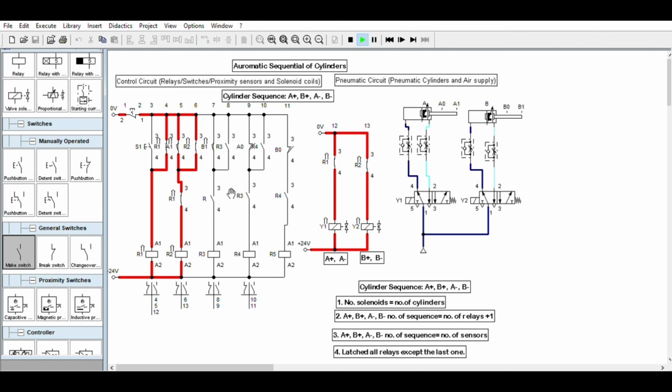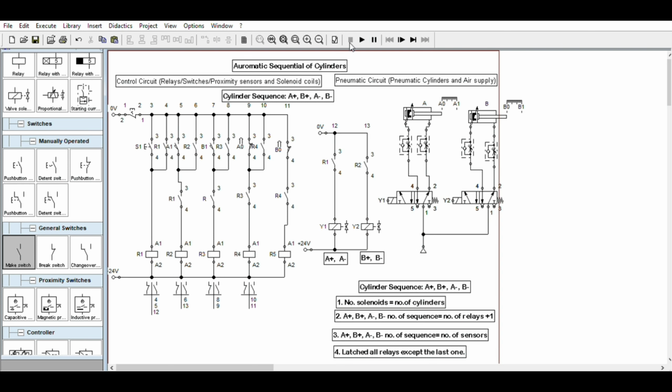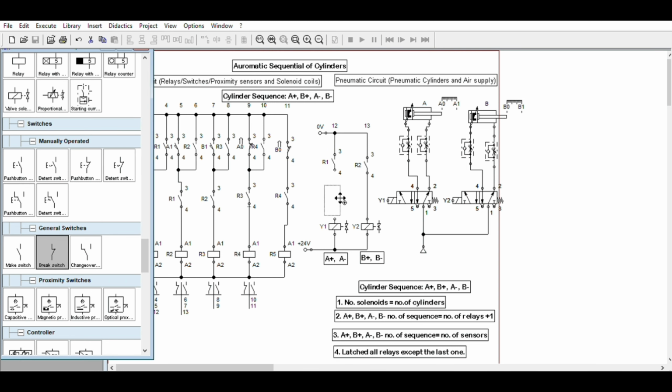Since we did not place the contact and no triggering of R3, R3 will turn off this one. That is hit by B1. They are now in extended position. Turn off. So again, the one that turns off is normally closed. And R3. So place this one R2 to continue the operation, and we need R3 to open, and that will be a normally closed contact.